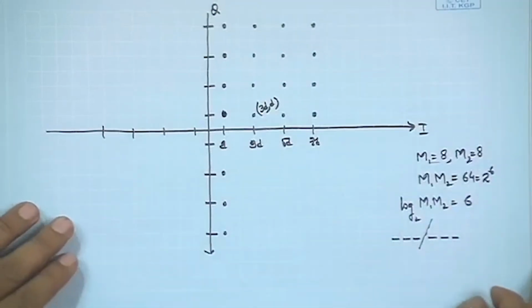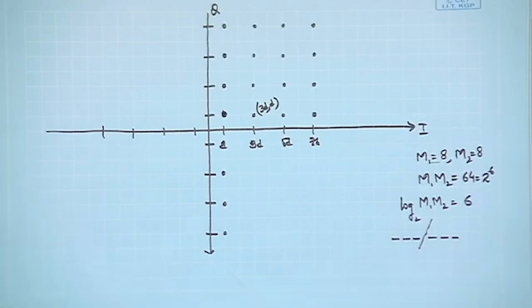Now, an important question here could be whether the gray coding that we had discussed earlier would still be applicable in this case. As I had mentioned, in case of phase shift keying, you could still do gray coding by allocating the bits in a pattern where the neighboring 2 constellation points differ at most in 1 bit location. The same thing can be done in this particular case as well.